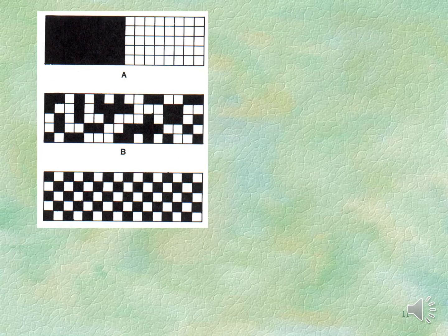So when we start to mix powder, if I put in black particles and white particles, at the initial stage they are totally segregated. If I introduce a stirrer into the container and let it mix for some time, after a while I could get something like this, which is what we call the random mixture. We know that in theory a perfect mixture is not possible.